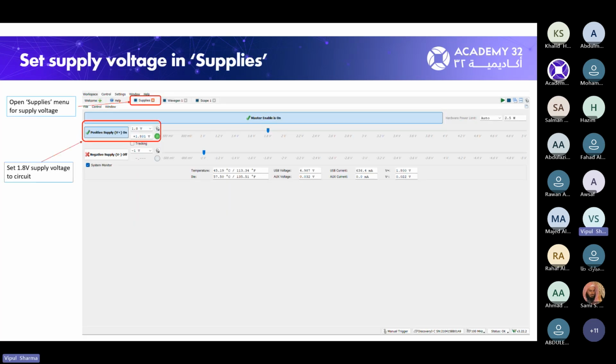So the first thing for any circuit to be given is supply voltages. Without giving supply voltages, there will be no proper DC biasing for that circuit. You cannot make your circuit work if you just apply an input signal and there is no power supply; obviously that circuit will not work. The first signal which should be applied to the circuit is the power supply.